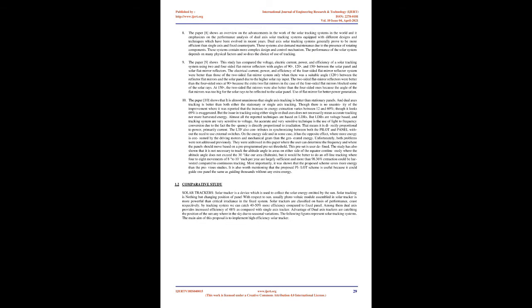2. Paper 2 shows that the gains generated by the tracking mechanism were more substantial on sunny days or on days with few clouds. On cloudy or rainy days, this gain was observed to be reduced and sometimes slightly negative, in cases when the panel was stationary owing to the luminosity below the limit. During the period of one day, this increase is less than or equal to 0 at midday, increasing as the time distances from this period, during the morning as well as in the afternoon.